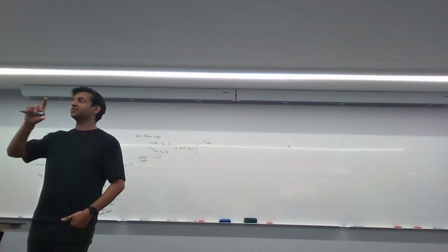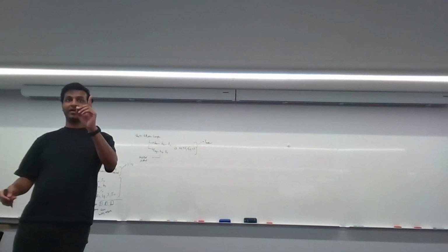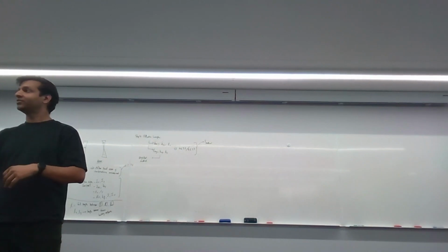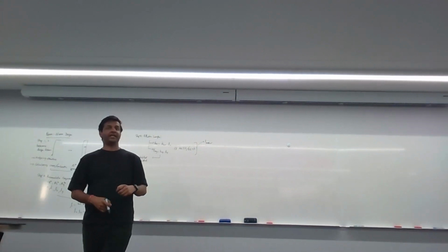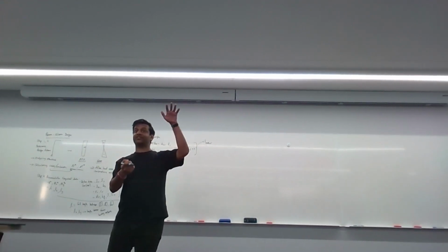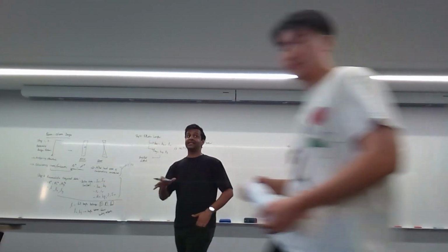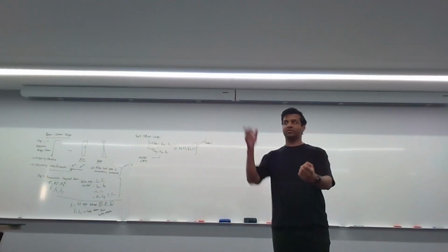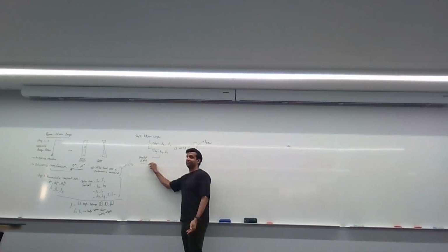In a pin, pin case, the effective length of the column is equal to the length of the column because K is equal to 1 for pin, pin. Remember, if you have fix, fix, what's K equal to? 0.7. And if it's pinned on one side, fixed on the other, it's 0.85, and so on. So in the idealized method, that is if you're able to say correctly the bottom is pinned, the top is fixed, or whatever, that's the idealized method, also known as the simplified method.